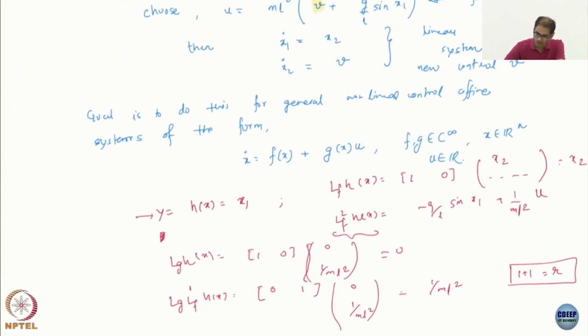So, we start as usual with this nice control affine system. We are used to this, right, that the system is basically affine in the control. These f and g are all in Rn. So, states are in Rn, f is an n vector, g is an n vector. We already know this is called the drift vector field, this is called the control vector field. Here I have written it in this way where there is only one control, a scalar, like a single input system. You can of course generalize it. It just makes the presentation very complicated, therefore I have restricted to the single input case, and everything is smooth. I have assumed all the nice properties.